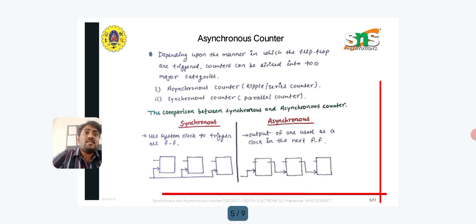In an asynchronous counter, flip-flops are triggered sequentially. The output of a flip-flop serves as the clock input for the next flip-flop. Depending upon the manner in which the flip-flops are triggered, counters can be divided into two major categories, that is, asynchronous counter and synchronous counter.